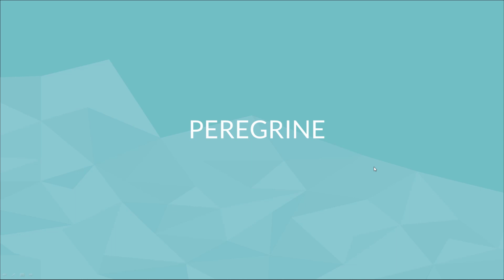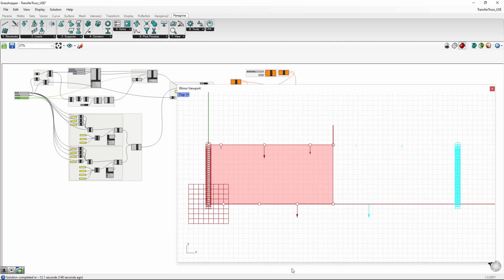So let's take a quick look at a mirroring example in Peregrine. So here I recreated the problem with the initial setup taking not much longer than about 30 minutes, and the thing to notice is that the problem is symmetrical about this center line here on the vertical axis, and that allows us to take advantage of the mirror functionality. Essentially all I did was set up one half of the problem, so one half of the design domain, one half of the supports, and one half of the loading, and you can see here in light blue on the right hand side the supports and the loading are mirrored, and what's going to happen is that we're going to get an optimized structure in this half that will then be reflected about that center line.